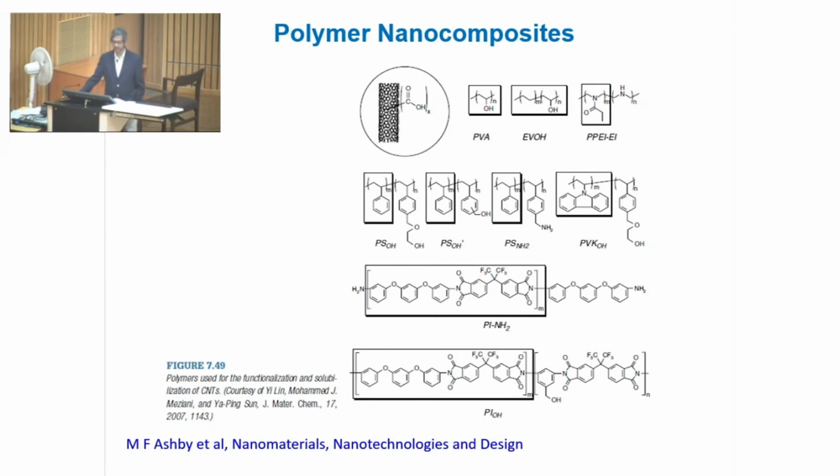Finally, the interfacial bonding between the CNTs and the polymer is very important. It is believed that the efficiency of the load transfer in a nanocomposite depends on the interfacial characteristics of the reinforced phase in the matrix. So, in the case of a polymer matrix nanocomposite reinforced by CNTs, the main mechanism of load transfer is mechanical interlocking between the CNT and the matrix.